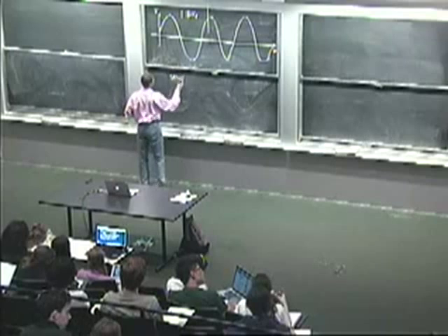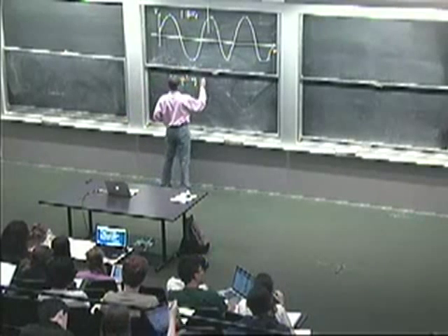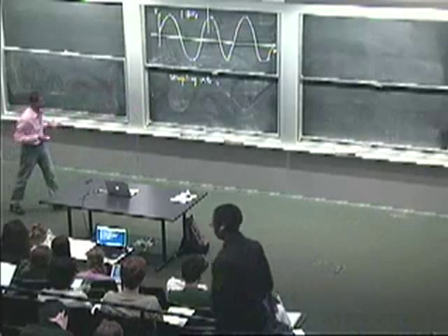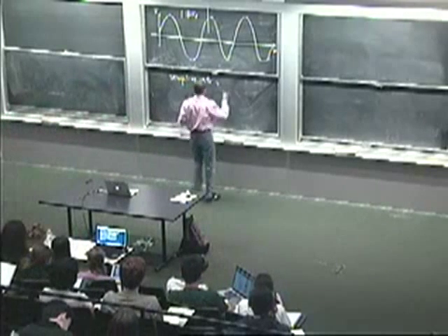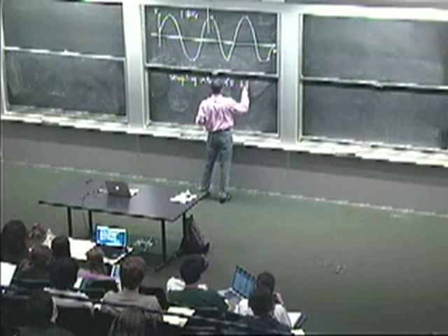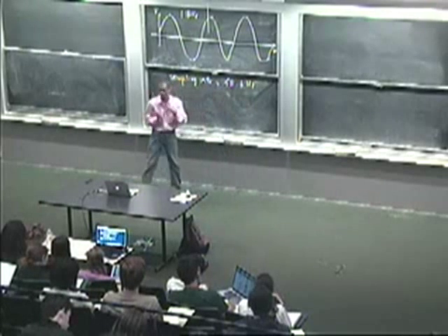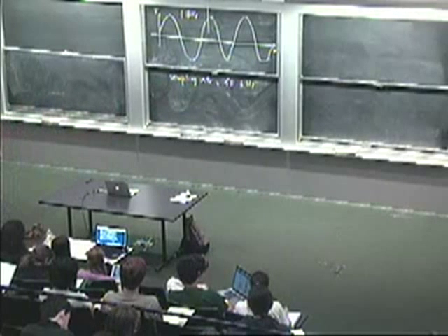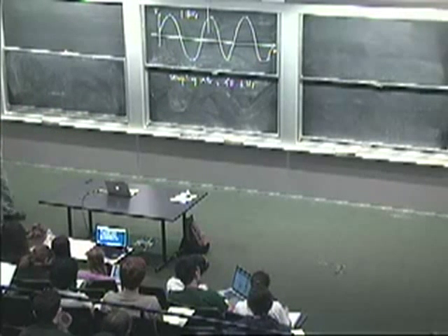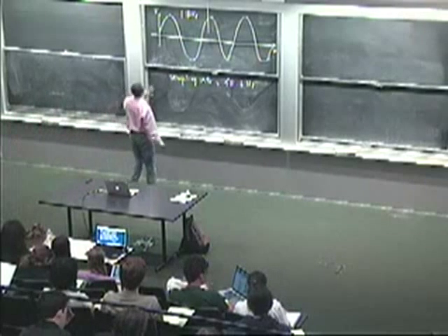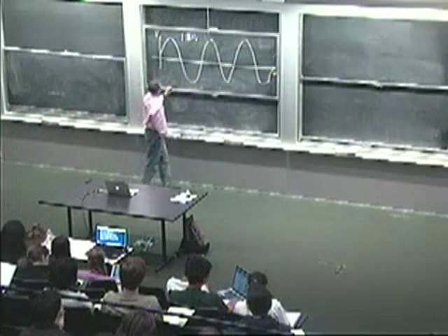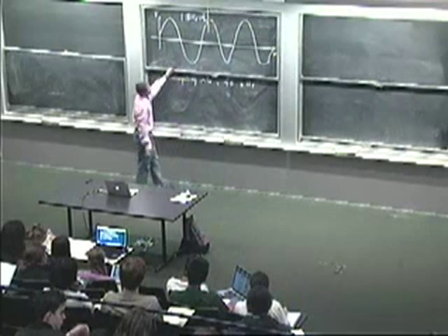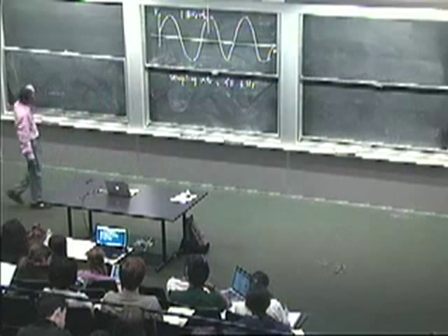The sampling rate can be anything. By default, in this system, we've picked the highest possible sampling rate of 48 kilohertz. In some cases, you might have to yank it down. You might have to go as low as 8 kilohertz, but 48 kilohertz seems to work in the lab. It works on a bunch of machines that I've looked at. So we have two things. We have the 1 kilohertz, which is the carrier waveform. We'll use the notation FC for that. And we can receive samples at 48 kilohertz.